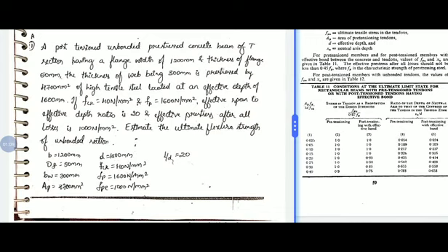So by seeing the question we can decide it is a post tensioned unbonded section. So since it is unbonded, it will be either case 3 or case 4. Now let us go for the section. It is a T section. It means it is a flanged section. So flanged section means it is case 4. Unbonded flanged section is case 4.